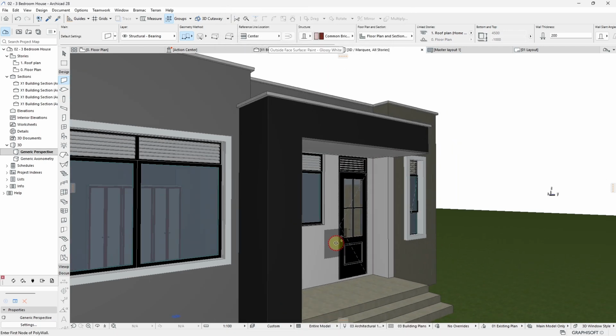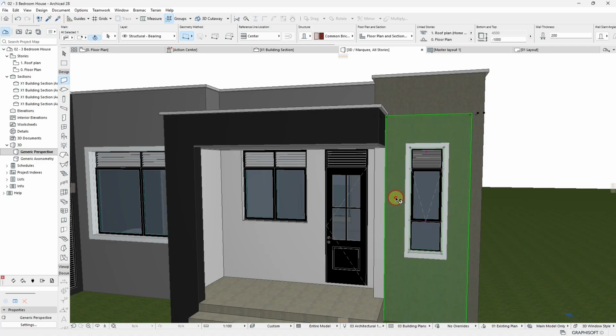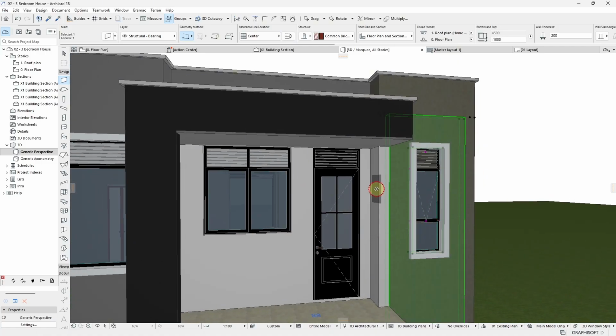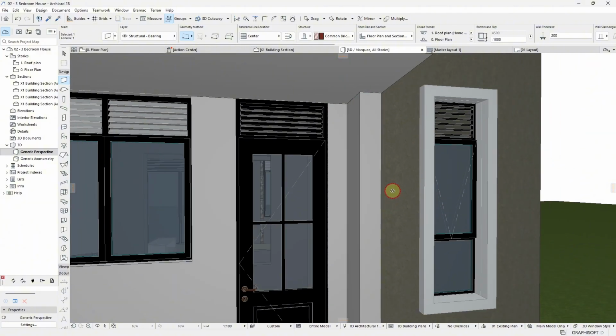And now there's one common problem that usually happens. And actually, I thank God it came up. You see now here, sometimes you want this paint to move seamlessly, to blend with this part here. But you find out that your wall inside is blocking it. If this ever happens to you, what you need to do is go to the settings of this particular wall.